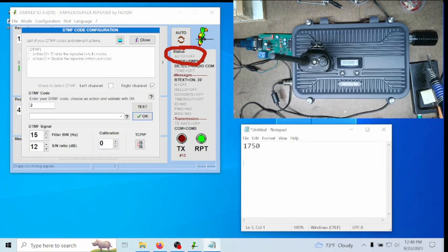The software is going to be looking for tones that are 1742.5 and 1757.5. This is 15 hertz peak to peak. So that's what the software is going to be listening to. It lets you give the software a little leeway because not every sound card is going to be perfect when the tones come across. So that's what that's for.